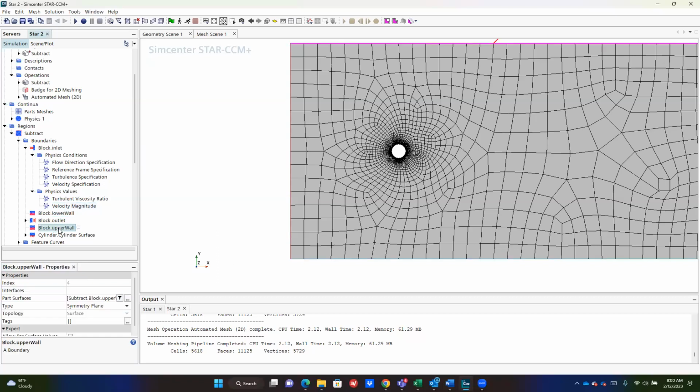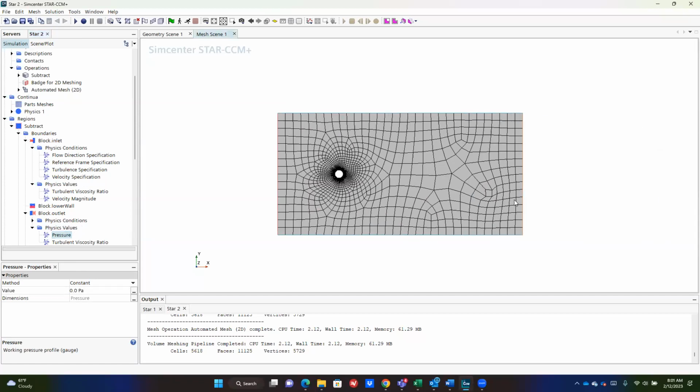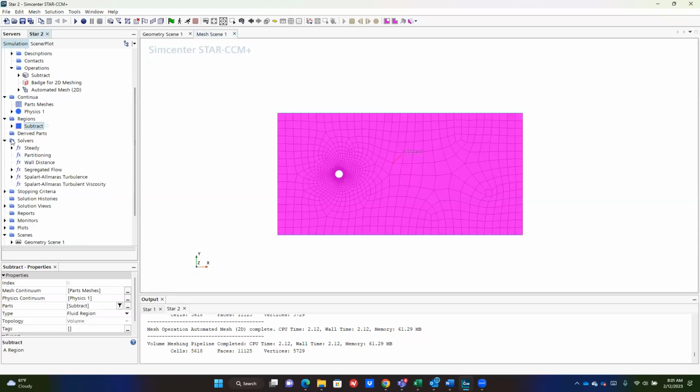These are basically no flux through the boundary conditions. And then we basically set a pressure. I'm just going to use 0 pressure. It's a gauge pressure. So it's basically going to specify 0 pressure here and propagate pressure upstream, and it's going to specify 100 meters per second velocity here, and velocity propagates downstream.